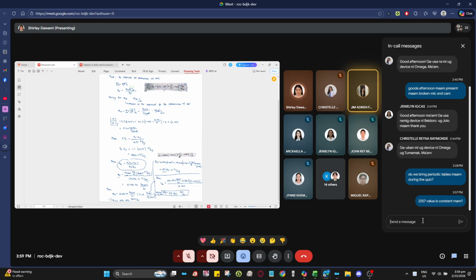Excuse me, ma'am. Is 2257 a constant? Yes, this 2257 is the theoretical latent heat of water at 100 degrees Celsius. It is constant if your hs minus hf is in kilojoule per kilogram.